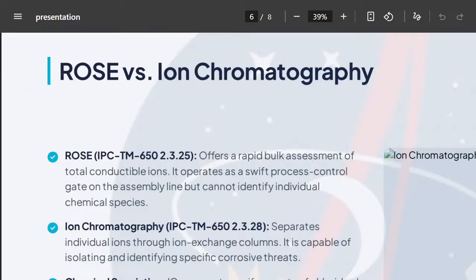Physical dissolution. So what do we mean by dissolution? These contaminants, including the adipic acid, other fluxes and all ionic contaminants, will be dissolved in the isopropyl alcohol. When they are dissolved in the isopropyl alcohol, the resistivity changes. Whenever you add something to the original substance and turn it impure, the resistivity will also change because the matter is changed, right?